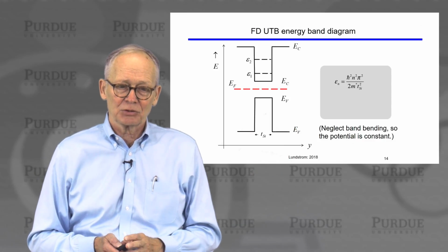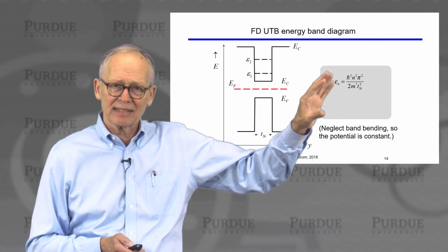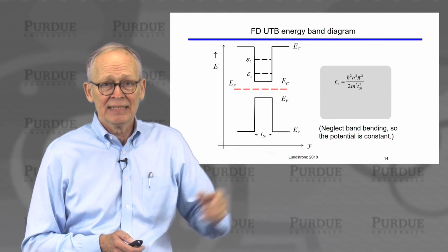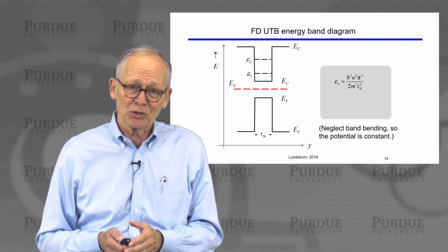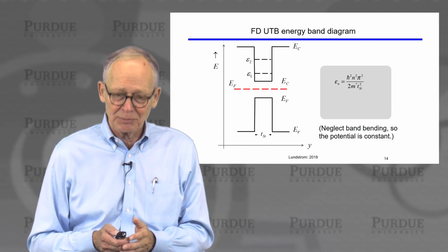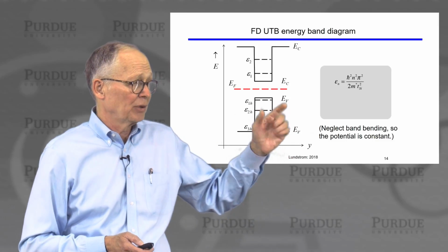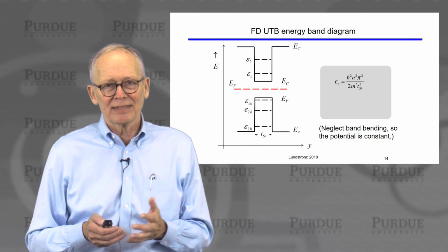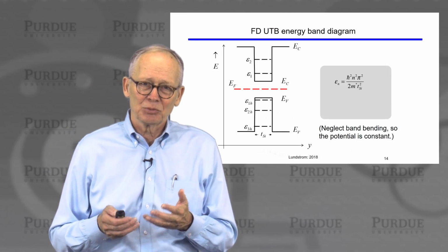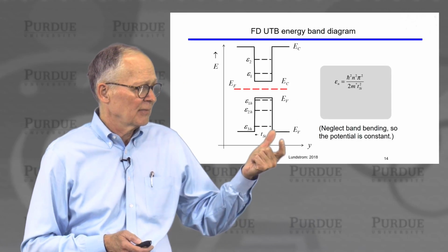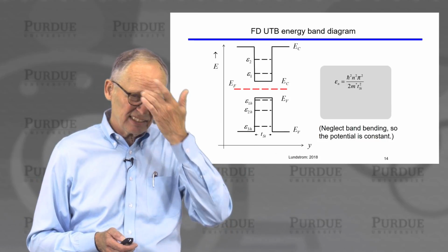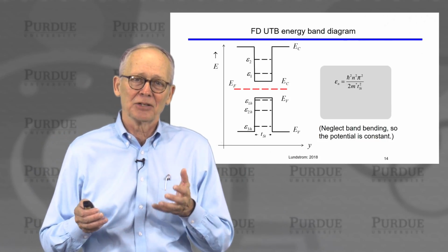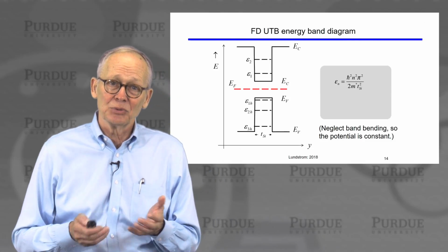There will be discrete energy levels that we can calculate with particle in a box expressions if we have an infinitely high barrier. If we have a finite barrier, we have to be a little more careful, but the results are similar. We also have confined holes, so we have confined states there. So it's a little more complicated situation, but what happens is really not so different, we will see. So T sub Si will be the thickness of the silicon. It's not hundreds of micrometers as it is in a modern bulk wafer. It's now just a few nanometers thick.